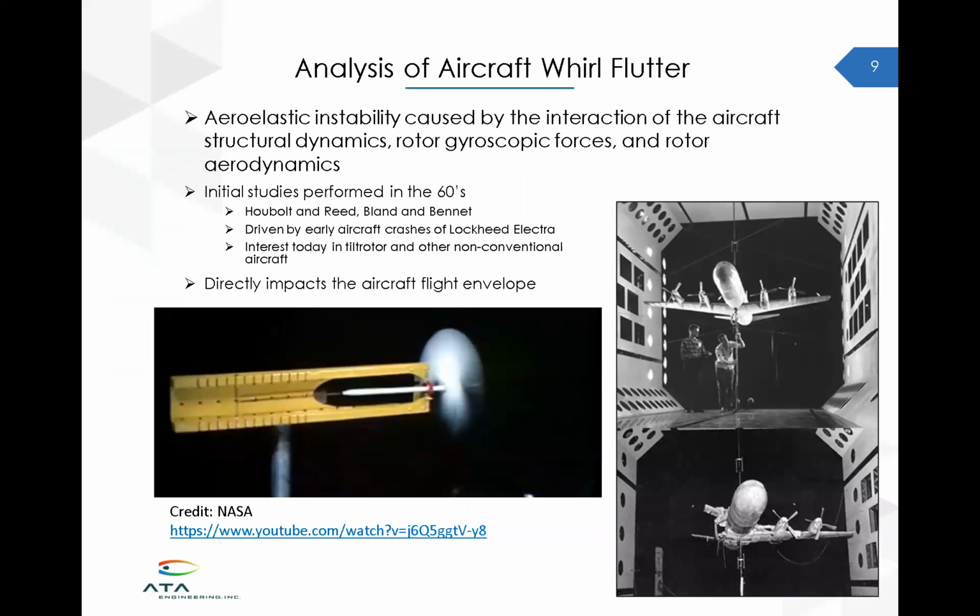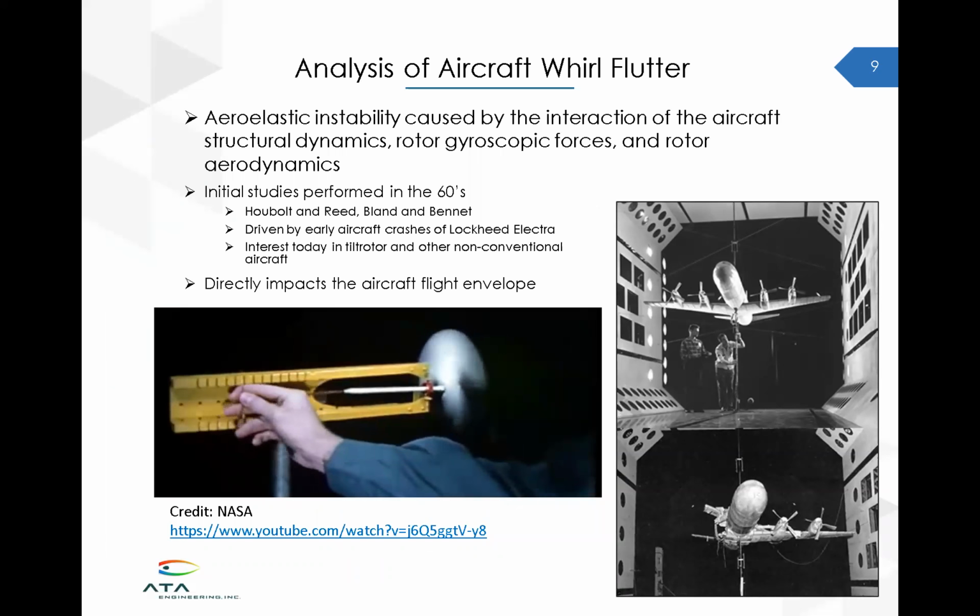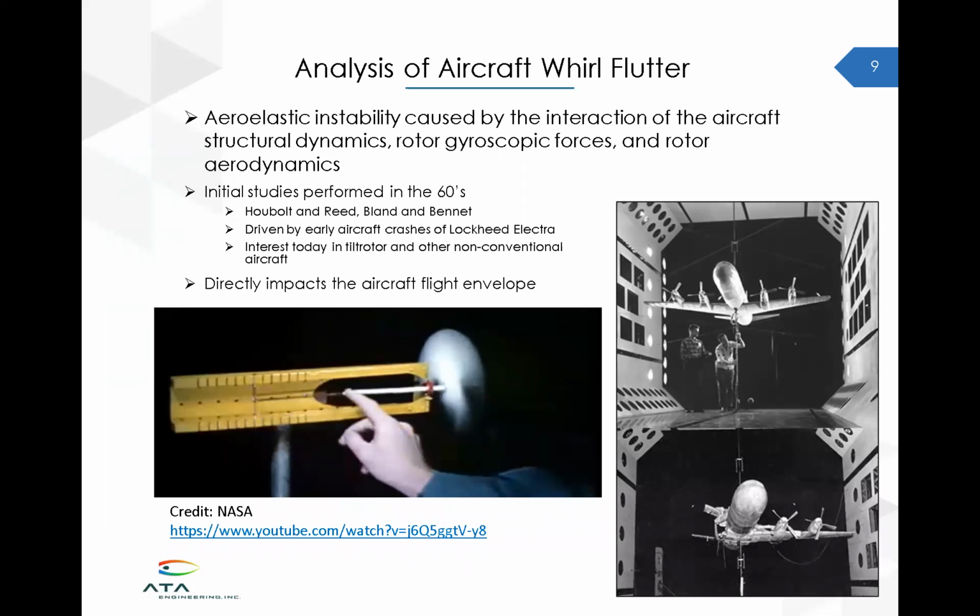One of the main reasons we wanted to use this tool was to look at whirl flutter. Whirl flutter is an aeroelastic instability that's exploiting the coupling between the aircraft structural dynamics, so the flexibility of the wing, the rotor gyroscopic forces, and then the rotor aerodynamics themselves.